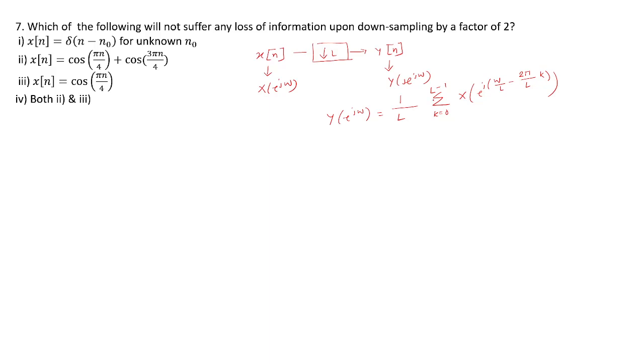So basically you can see the downsampled signal becomes periodic with L pi, but any discrete time signal is periodic with 2 pi, so we cannot violate the fundamental conditions. So this results in copies of the original spectrum with an amplitude scaling factor and frequency shifted versions of the spectrum. So this is the relation between the DTFT of the downsampled sequence and the original sequence. You get scaled amplitude and frequency shifted versions of the original spectrum.